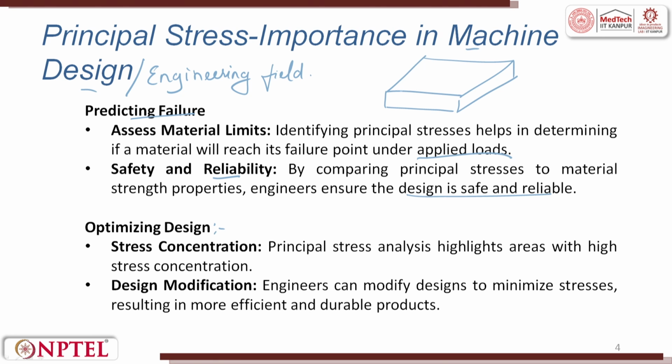Today, we have started making grooves in the flat plate, through which the stress concentration points are eliminated and through which the lubricants can easily flow. By doing so, the friction is reduced. So, once the friction is reduced, the longevity of the component is enhanced.